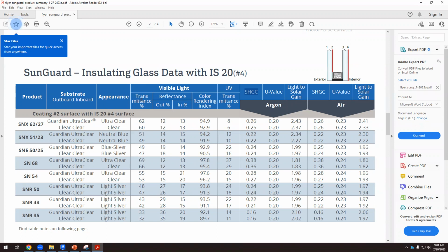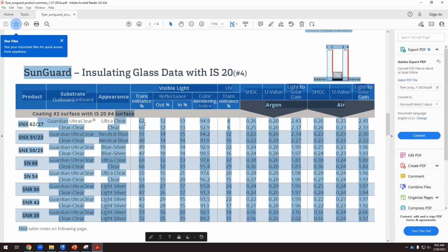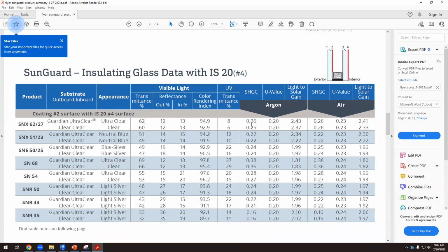So we have this solar radiation: part of it is heat, another part is light. They are smart enough to create a coating that prevents heat from entering, but allows light to enter the building. How do they do it? Chemistry. But this is their goal: to increase the visible transmittance and to reduce the solar heat gain coefficient.